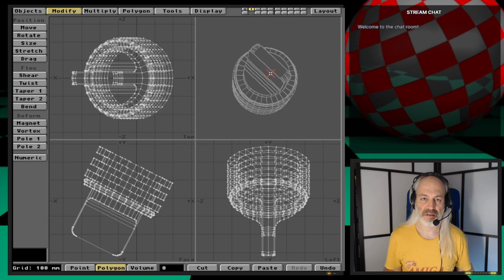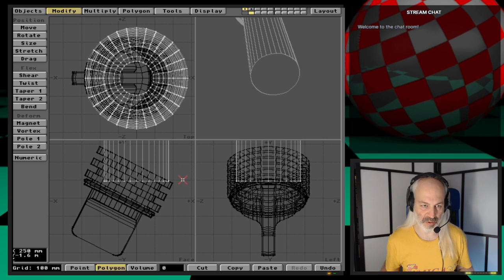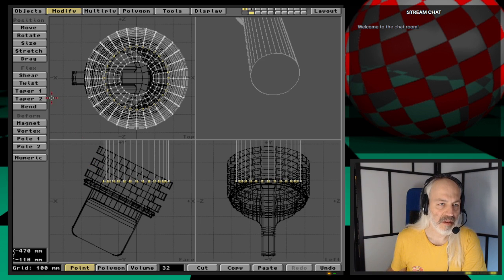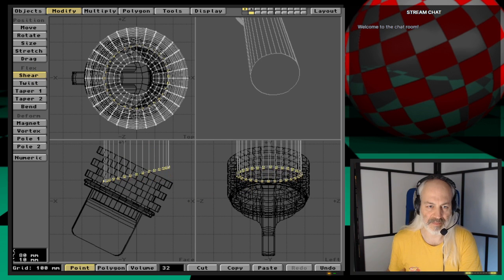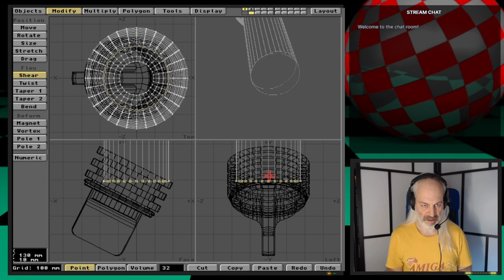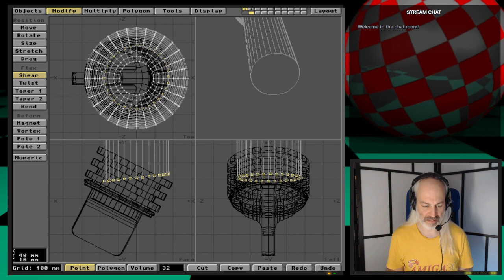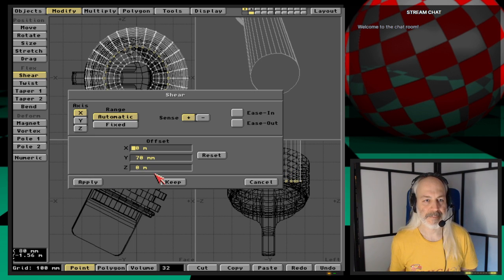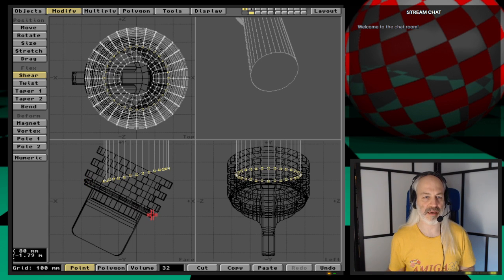So great. Now I can apply Boolean to both of these. I will need to move these. There is this shear. I'm going to be shearing that there, but towards the other point. So perhaps pressing once here and then undo. Press here perhaps to change the center, and then no, so I have to go numeric. Okay, so the axis is, apply. The axis is X. Undo. Yes, the axis is correct.